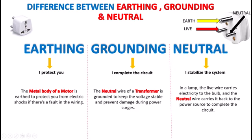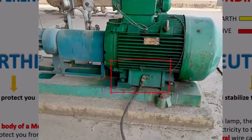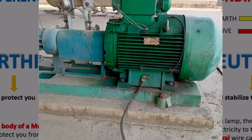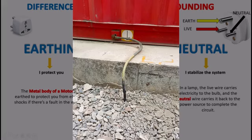Let's take a closer look at how the motor body is earthed to protect you. You can see in the pictures how the metal body of the motor is connected to the earth. This earthing process is crucial because it provides a safe path for electricity to flow if there's a fault in the wiring. If, for any reason, a live wire inside the motor touches the metal body, the current would normally flow through the motor's outer casing and could cause a dangerous electric shock. But by earthing the motor body, the fault current is safely directed to the ground. This way, it prevents you from being electrocuted and protects you from harm.